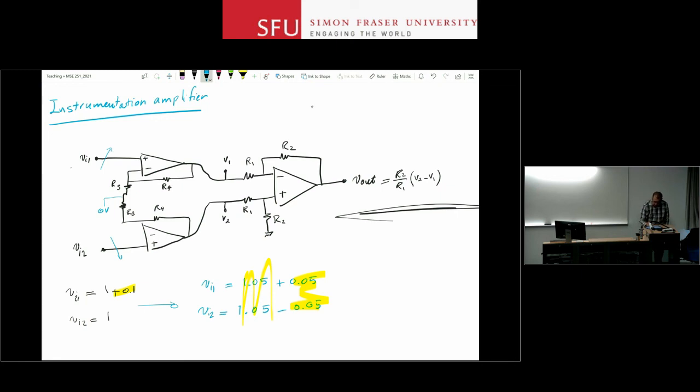I'm going to make an example here. You have one resistor here, equal value. This voltage goes up, this voltage goes down. What do you think this voltage is going to be? For a differential change at the two ends of these two resistors, that voltage remains 0. So without connecting that middle point to 0 volt, you actually get 0 volt between them, right?